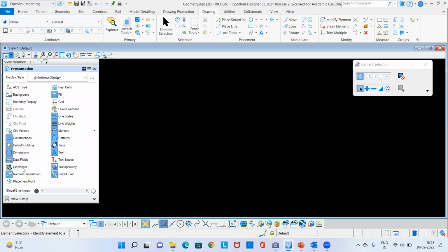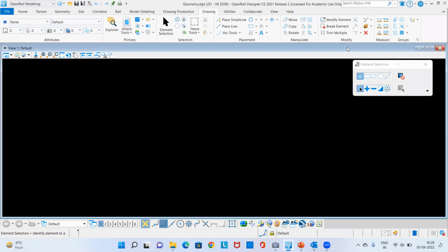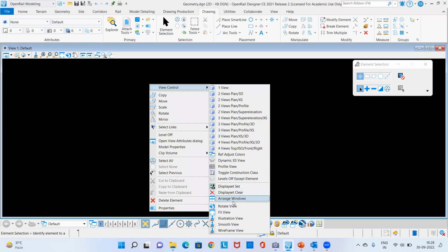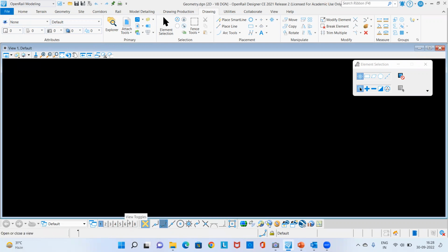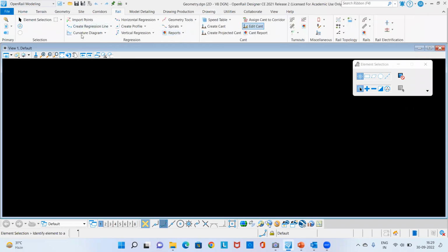So if you go here, you see, you don't see that background map option here, as I said. So here the GCS is not set. So the data set is without the GCS. That's why, until you set that geographic coordinate system, this background map won't appear here. You will have all these view controls similar, all the views you can open manually. All the tools which you have in OpenRoads Designer, except this is an extra tool, a dedicated tool for rail design. You can see it here.